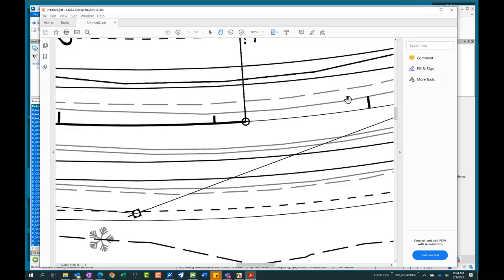It's okay because the MicroStation seed file is identical to the OpenRoad seed file. They're identical. But the OpenSite seed files have a different alignment, different civil schema, and that's where we would wind up with problems.